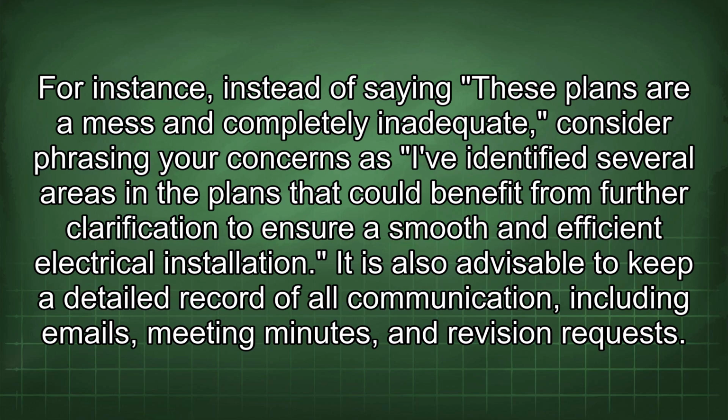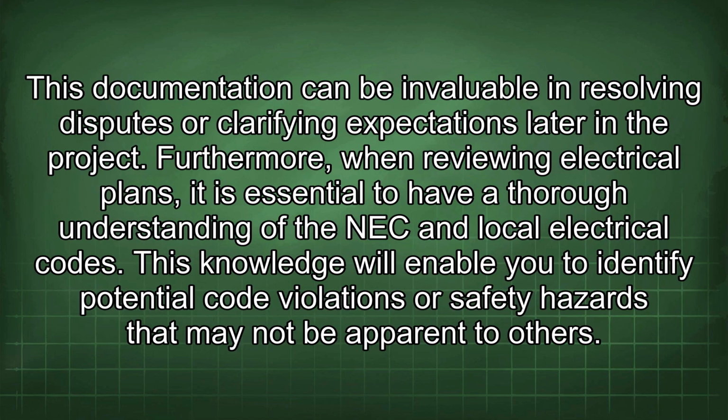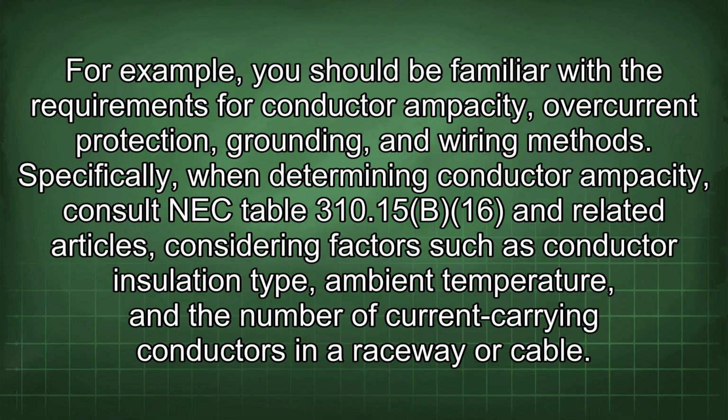It is also advisable to keep a detailed record of all communication, including emails, meeting minutes, and revision requests. This documentation can be invaluable in resolving disputes or clarifying expectations later in the project. Furthermore, when reviewing electrical plans, it is essential to have a thorough understanding of the NEC and local electrical codes. This knowledge will enable you to identify potential code violations or safety hazards that may not be apparent to others. For example, you should be familiar with the requirements for conductor ampacity, overcurrent protection, grounding, and wiring methods.